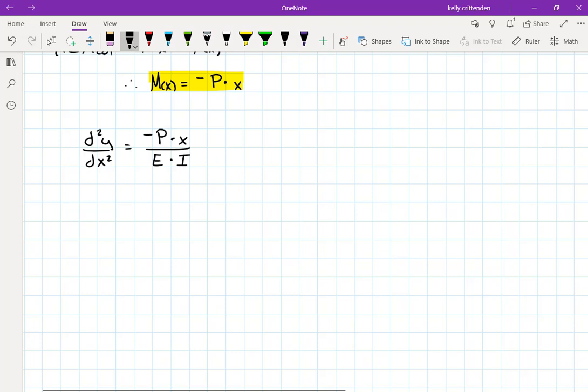So a large moment of inertia would make it not want to bend very much. E takes care of the material, and I takes care of the geometry. Is it an L beam or a C beam or a T or an I or whatever it is, and that's all summed up in that moment of inertia. So those two, which affect how the beam bends, are constants in the equation.